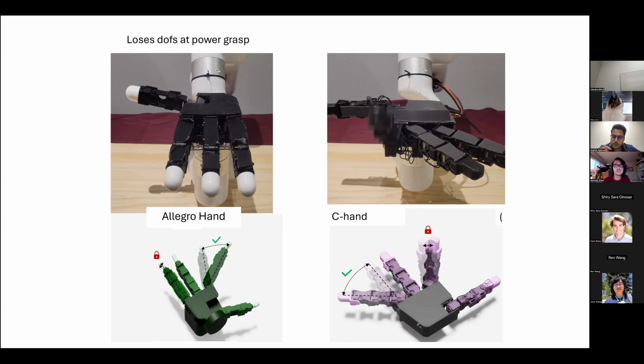So what that means is that there will be some pose for the finger in which the rotation axis gets aligned with the finger axis. And in that particular pose, you hit a singularity and the finger loses a degree of freedom. But what we did in the LEAP Hand is we switched the order of these motors so that the motor which controls the left to right movement of the finger occurs after the motor that controls the flexing. And what this leads to is that the axis of the rotation never aligns with the finger. And so we never lose a degree of freedom.